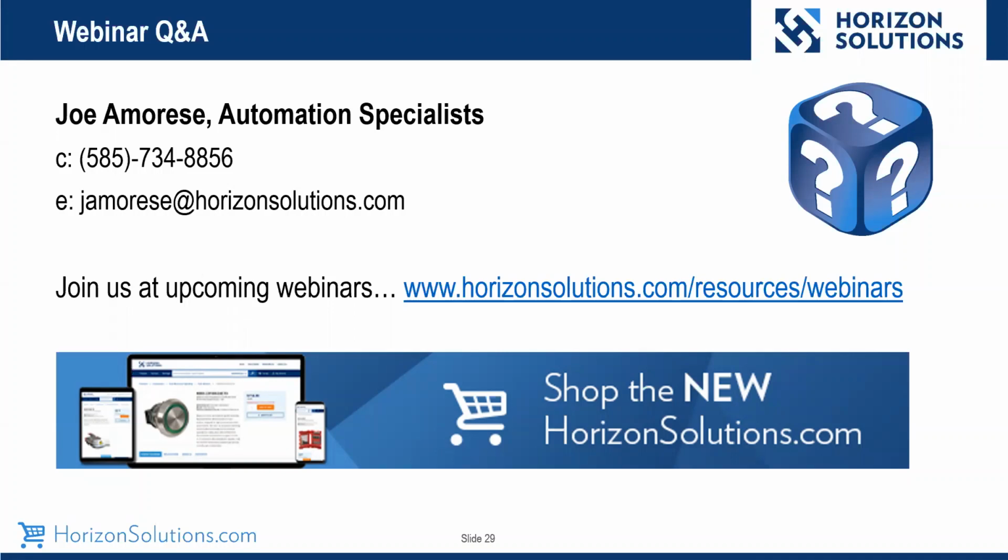But I think as the products evolve, we're going to start seeing more things with PoE. You have to remember, PoE is 48 volts with milliamps. You're running through 18 gauge, 20 gauge, 24 gauge wires. So it's low current draw products. But the most product I see are vision cameras that are doing machine vision, and things like barcode readers and things like that in the machine world.